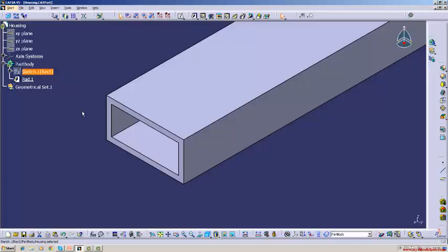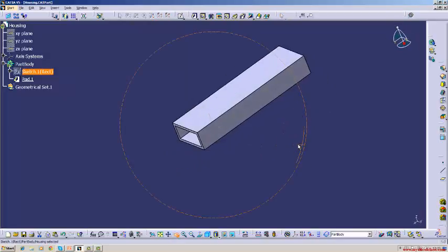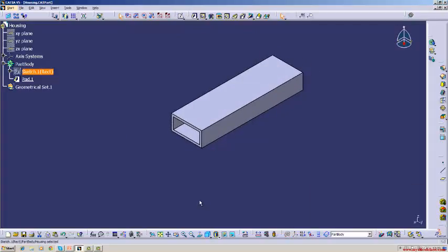Now, see here we have seen, since we have extruded, it has a pocket, a rectangular hole inside throughout the length. I will show you. Clicking this, you can see, throughout the length. Okay. But in many cases, we don't need the hole to be throughout the length. Then we cannot use pad to create a pocket, but we can do it, though it's a little bit complicated. What we can use is another command called pocket. This command we can use to create a blind hole.